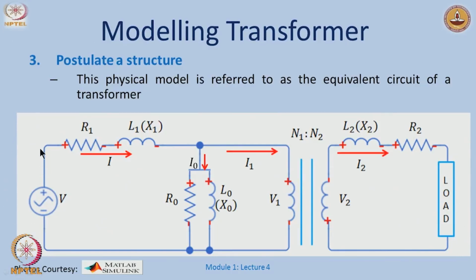I apply a voltage here which is equal to the rated voltage, then most of the current consumed would just be here, and based on the measurements of the power and the current and so on, I could estimate what are these guys, what is R, what is L, just by the relation between voltage, the current and the power, that we call in our lab experiments as the no load test.